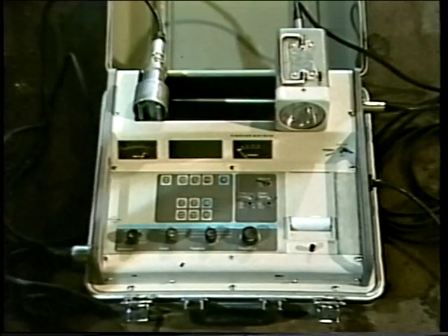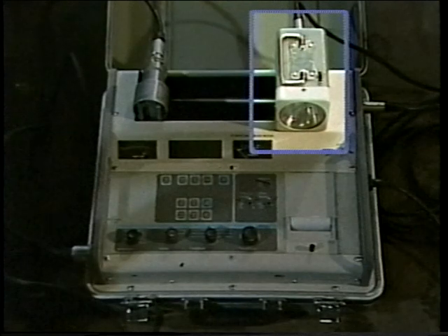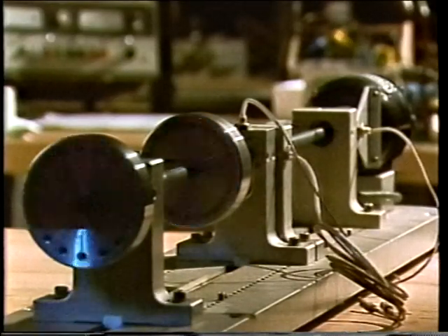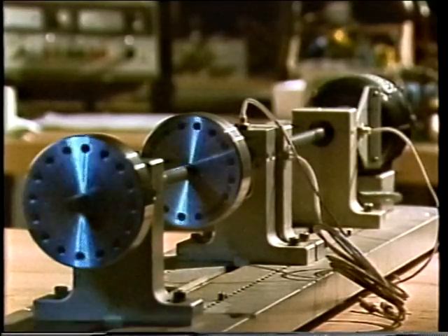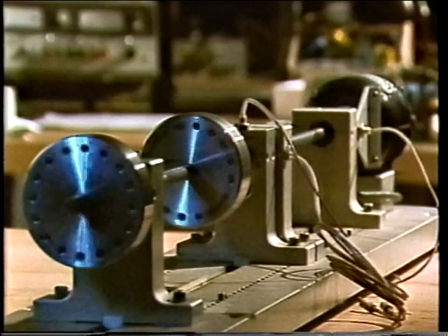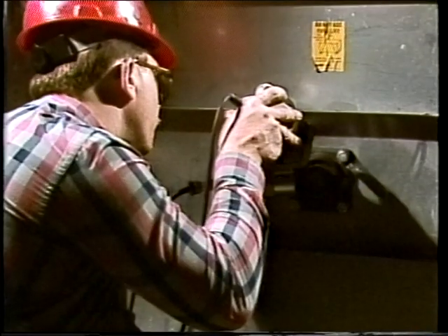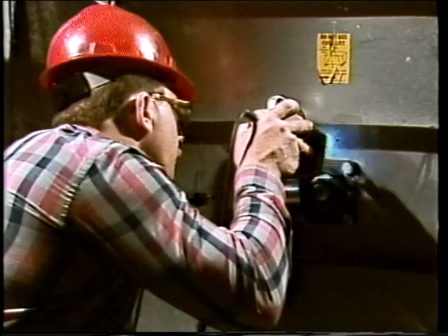Many vibration analyzers have a built-in strobe-type tachometer that can be used to determine a machine's speed. But remember, a machine will appear stationary when a strobe light flashes at a frequency equal to the speed of the machine, so you'll have to be careful not to forget that the machine is moving. It's sometimes difficult to tell if the strobe light being used is flashing at the correct speed.